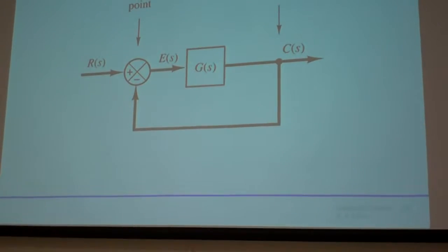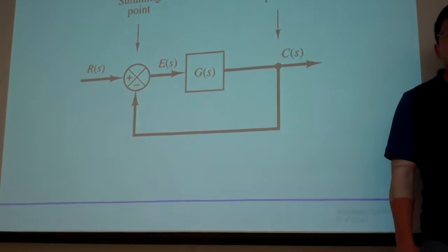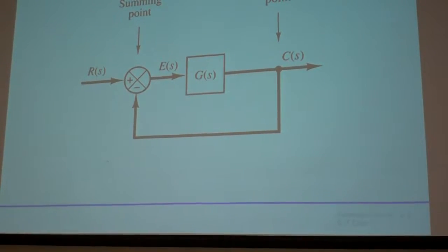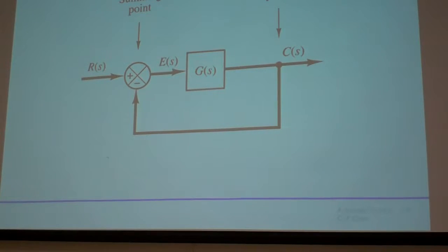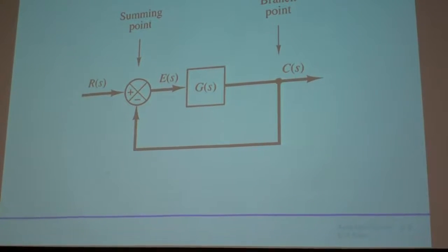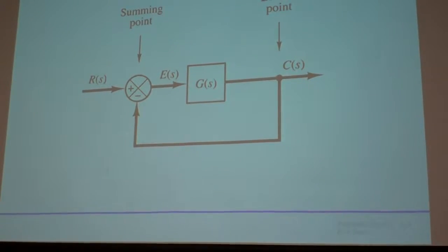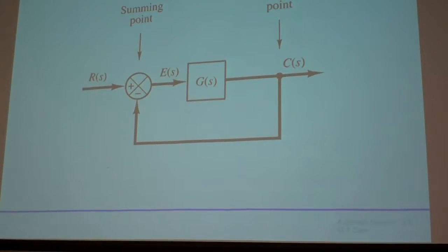Okay, and you might ask me why we bother to learn the block diagrams, and again, as long as we have the input-output relation and stuff like this, then, for example, if we want to characterize the time response, just like the homework one I prepared for you, question one in homework 2. Okay, so basically we can take the Laplace transform and inverse Laplace transform to find out what is the response of C in the time domain with respect to this one. Okay, if you haven't started, I would suggest you start it right away for question 1, so you will see what I'm saying here. Okay, so that is for this diagram.